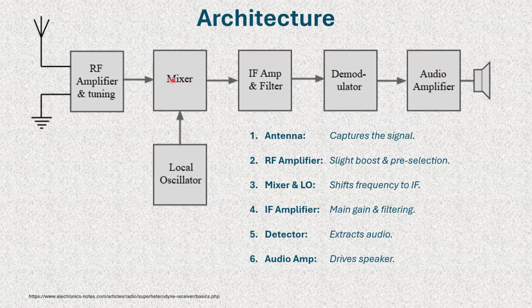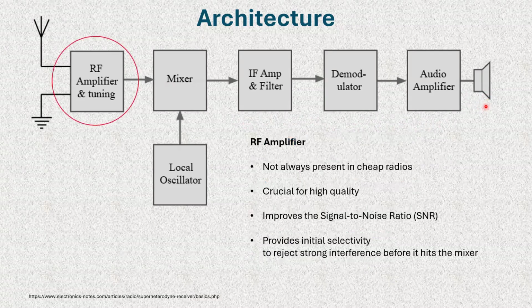So here's the idea of the heterodyning or the superheterodyne. Get whatever comes up before it gets processed further, convert that into that IF frequency. And then here, things can be nicely selected, nicely rejected, nicely processed, and reproduced for the intelligence, for whatever it is. In this case, it would be loudspeaker.